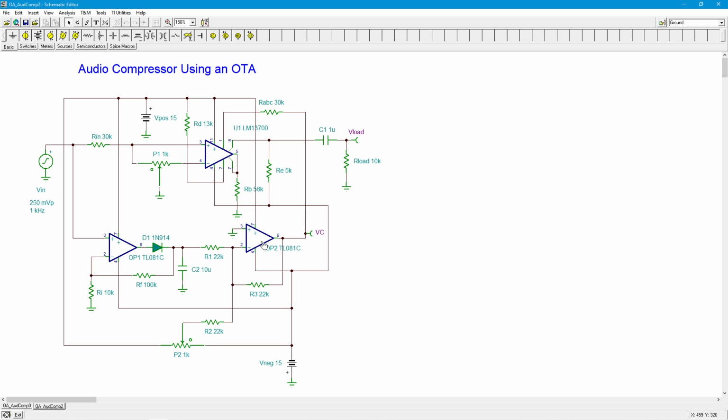So, you could use a quad op amp now. Use something like a TL084 or an LF347. Use two for here. Use another one for the input buffer. Use another one for the output drive. And you could make that adjustable. You just turn this load into a little pot, tap that off, go into a unity gain buffer on the output. Boom, off you go.